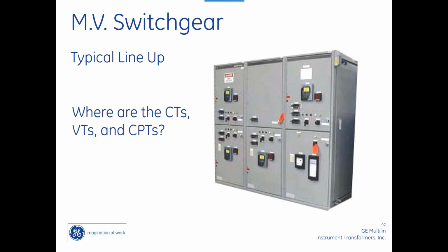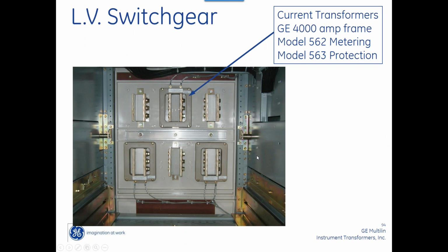Back to the slide with the staggered CTs. Spencer, what do you want on the staggered CTs? Can you stack the CTs? Yeah, I could put another CT. Depending on how deep this bus bar is, and depending on the manufacturer, you may be able to put 2 or 3 CTs on there.